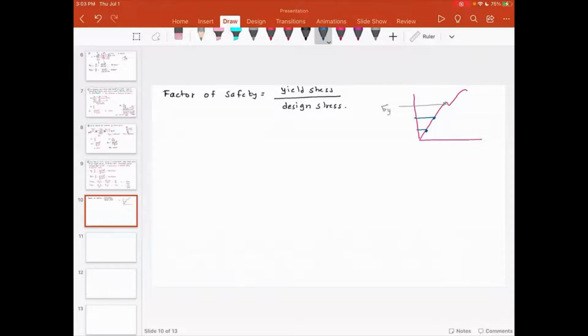For example, you come up with this great design, but the material that you obtain has some flaws. If it has some blowholes or impurities, and the material strength is not uniform, then clearly, even though your analysis is good, unfortunately, since the material does not have the properties that you initially anticipated, the component is going to fail.